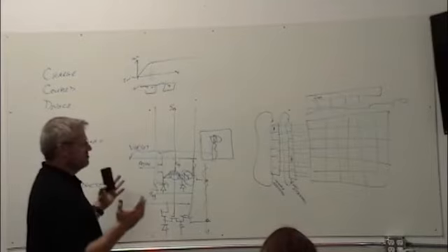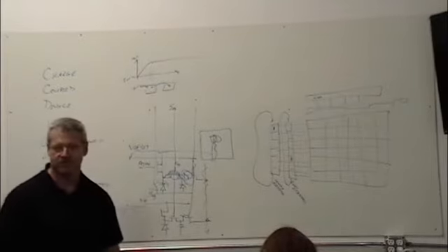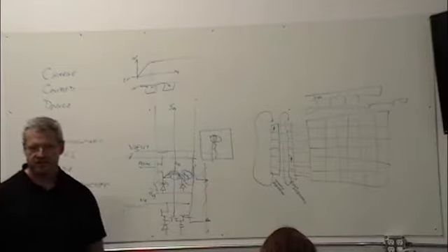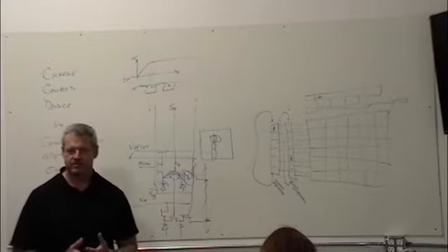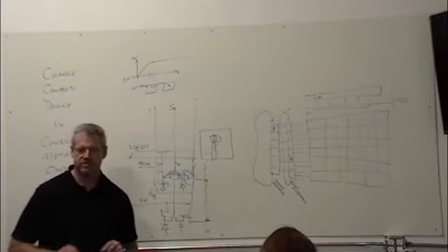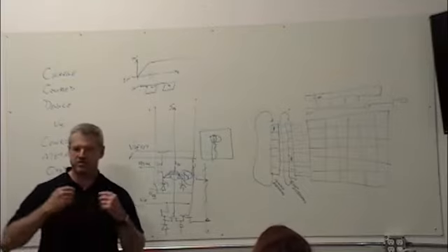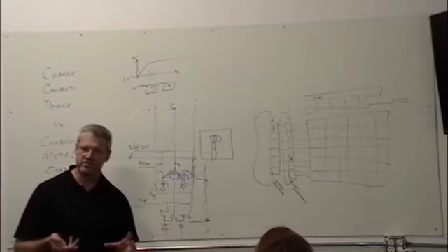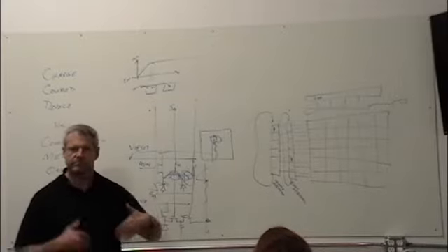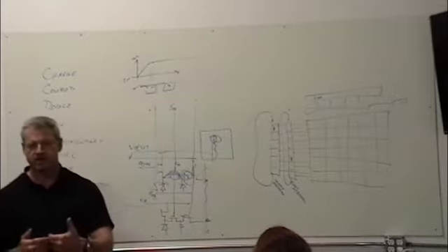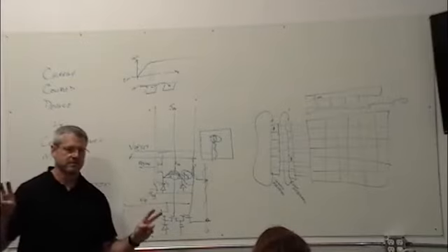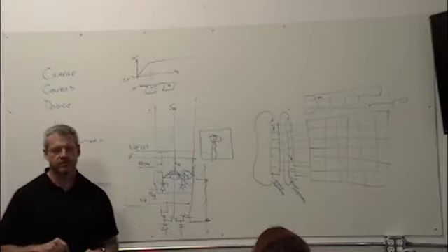These are the big major differences between a CCD and CMOS when you start hearing about it. If you're doing a digital single lens reflex, a lot of those are still CCDs. A lot of the point and shoot cameras are still CCDs. They can build the electronics fairly small and get you pretty good picture quality for the imager that's in it. Things have been slowly moving to CMOS because process technologies have been pushing CMOS to be better and better and better. For a good image, CCD is still the way to go, but you're going to pay more for it.